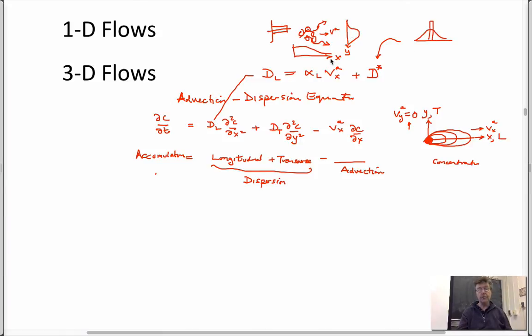We made the point that this mechanical mixing looks identical to diffusive transfer by Fick's law, and because they look the same, they all get lumped together in the same term, which is acted on by this second order differential. There's also a magnitude of this, representing not the longitudinal dispersion, but we could write it out also. It's worthwhile writing out.